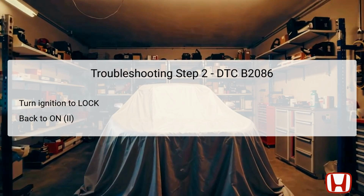In the second step, after clearing the DTCs, turn the ignition switch to the lock position and then back to the on position. This action helps in ensuring that all electrical systems are reinitialized, allowing the control units to reset. The transition from lock to on is vital for preparing the vehicle's electronics for the next diagnostic steps. It ensures that the control units involved with the power sliding door are in the correct mode for operation.